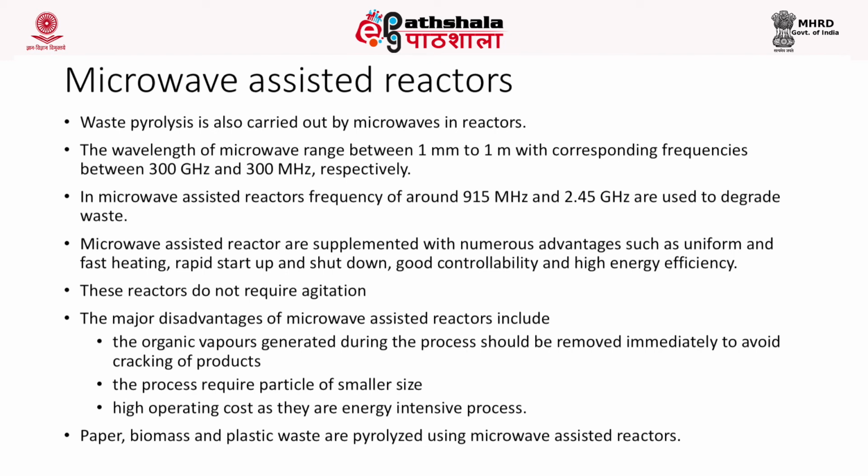The microwave assisted reactors are generally supplemented with a lot of advantages like uniform and fast heating, rapid startup and shutdown, good control and high energy efficiency. These reactors do not require any agitation. However, there are some disadvantages associated with the microwave assisted reactors.